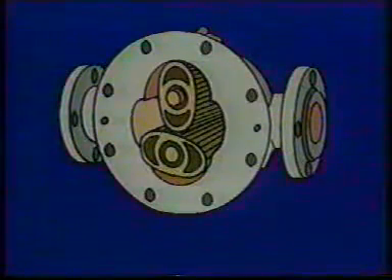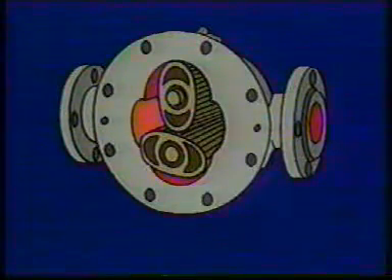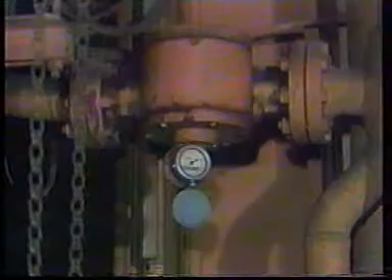through the flow meter. A variation of the lobed impeller flow meter is the oval gear flow meter. As you can see from this illustration, they look very much alike. Their principle of operation is exactly the same. However, they are designed somewhat differently. Instead of lobed impellers, there are two oval gears that mesh together and turn as fluid flows through the meter. A counter is usually attached to one of the oval gear shafts that counts the number of specific volumes of fluid transferred from the inlet to the outlet of the meter.